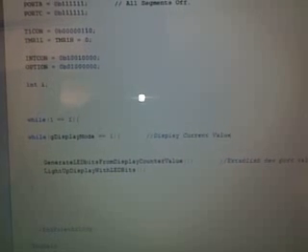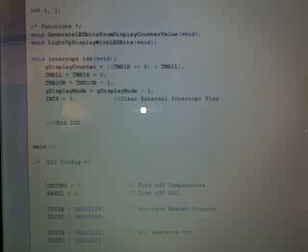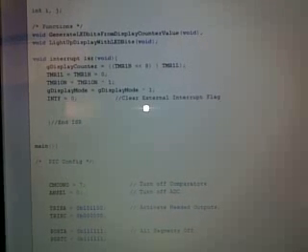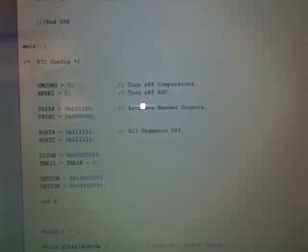And then for the final one, this program, count display final.c, it has a number of subroutines, but basically in the main loop, while it's in display mode, it loops and displays the current number in memory until an interrupt is seen, which brings it back and toggles the timer on and off, reads the new number from memory and loads it, and sends it back into timer mode or display mode.